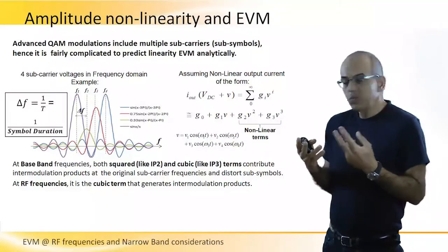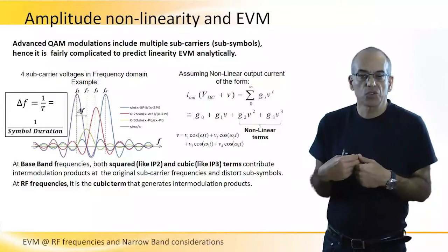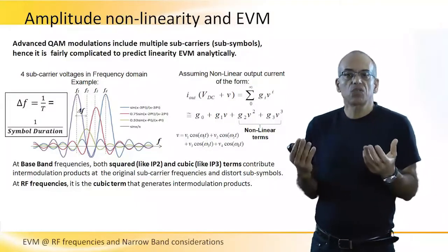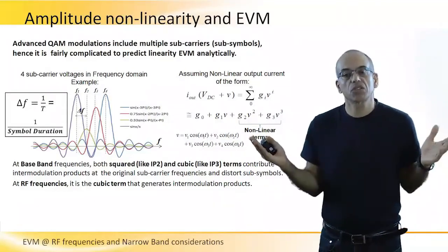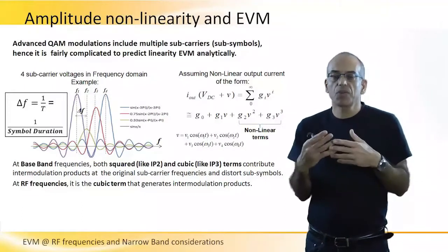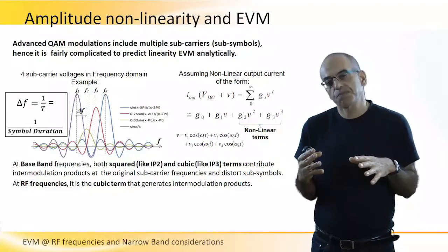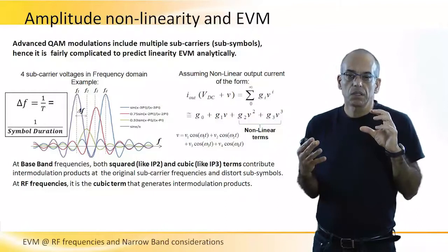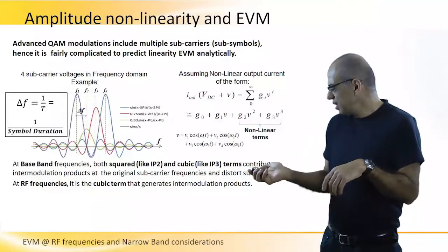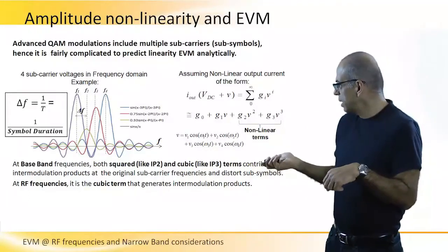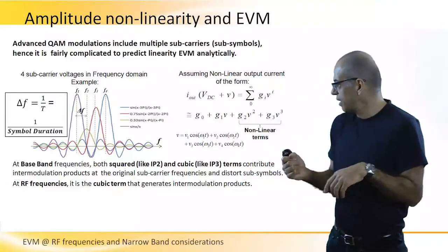But two tones will create other tones when they are introduced to a nonlinear circuit, and these two tones can still be within band because we have multiple carriers. So every couple, every three, every combination of frequencies that we can think of may create impairment frequencies that are in band. Okay, and it's very easy to show it through simple trigonometric exercises of multiplication.